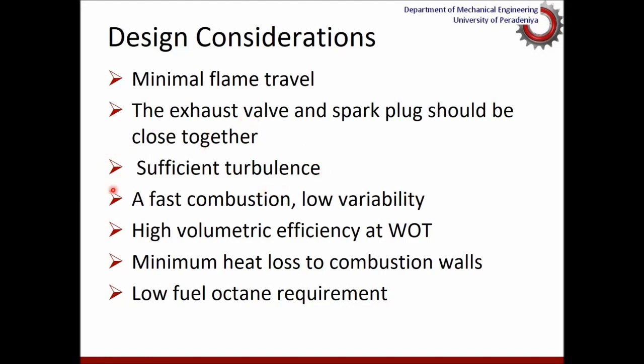And we need to create sufficient turbulence, of course, and we have to have a shorter combustion duration, quick burning, and the same burning characteristics in all cycles. High volumetric efficiency at wide open throttle conditions is required to produce more power, and minimum heat losses.